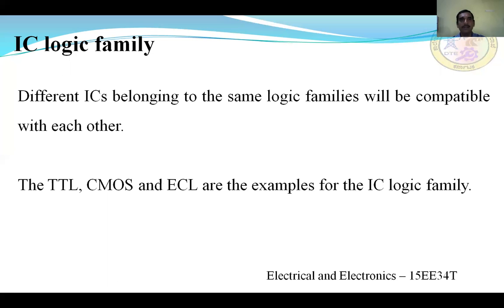So same thing, different ICs belonging to the same logic family will be compatible with each other. Some examples of IC logic families are TTL, that is transistor-transistor logic, CMOS, that is complementary metal oxide semiconductor, and ECL, emitter coupled logic. So these three are the examples of IC logic families.